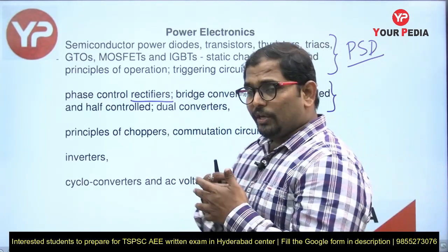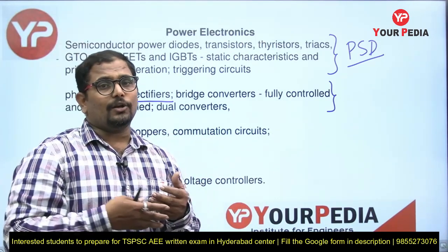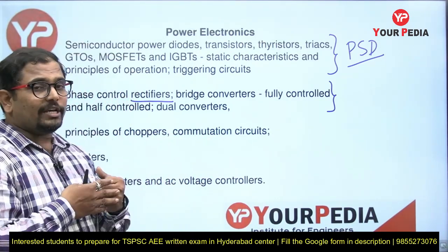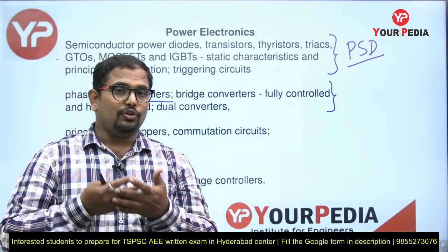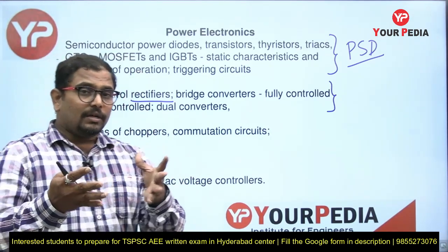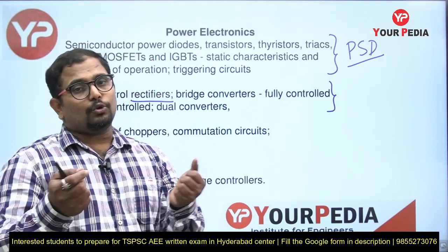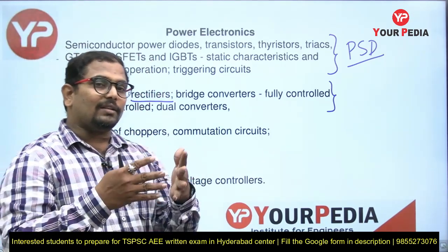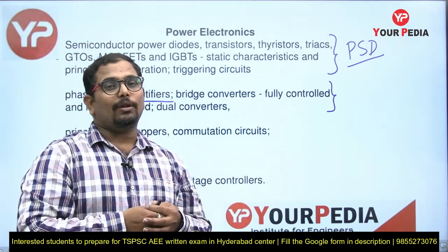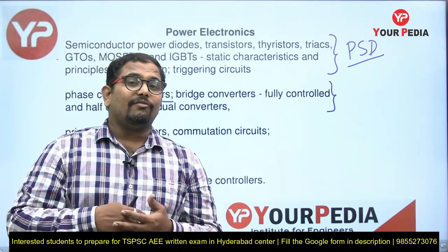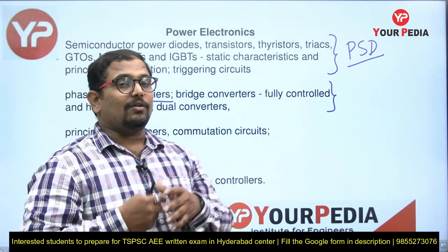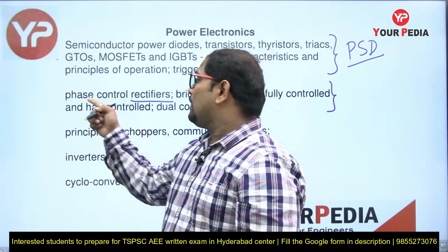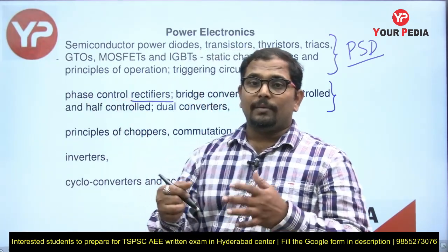If you require variable speed control or variable output voltage, you won't use a diode rectifier, because a diode rectifier gives a fixed output voltage, but the application requires a variable output voltage. So to get the variable output voltage, we'll take the rectifier concept and use a phase controlling concept by picking a device.